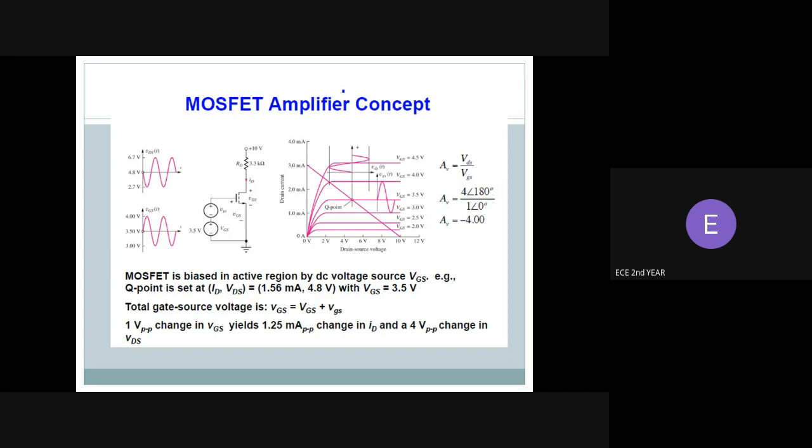current to flow. In other words, an enhancement MOSFET does not conduct when the gate-source voltage is less than the threshold voltage VTH, but as the gate forward bias increases, the drain current ID, also known as the drain-source current IDS, will also increase, similar to the bipolar transistor, making the E-MOSFET ideal for use in MOSFET amplifier circuits. The MOSFET's conductive channel can be seen as a variable resistance that is controlled by the gate.